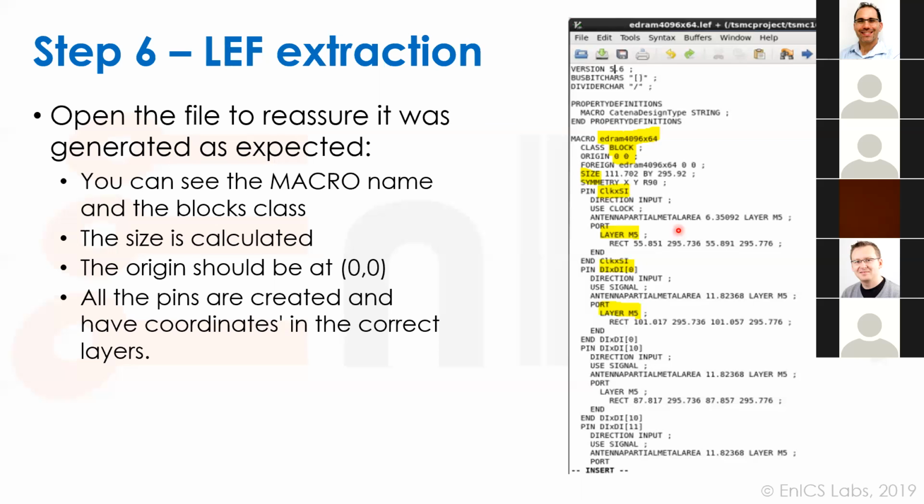Right. So in this case for the router, the tech file should have the information of what this ratio is that should be checked. And in the DRC rule deck, there's a special rule deck that all it does is check this antenna stuff. And that's per PDK, per process. Right.